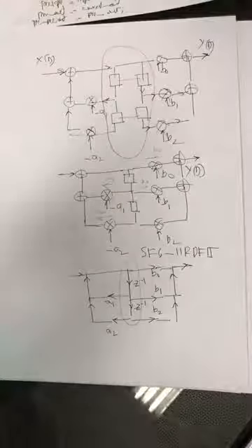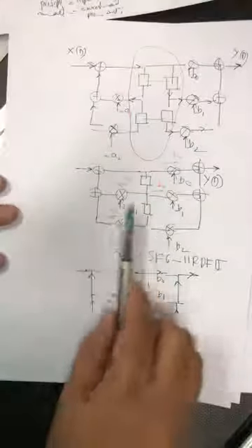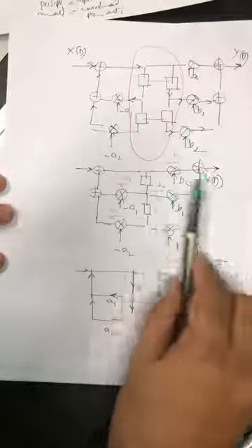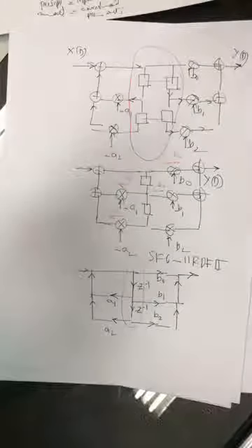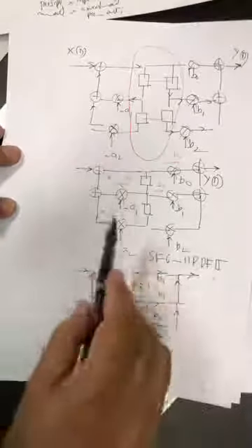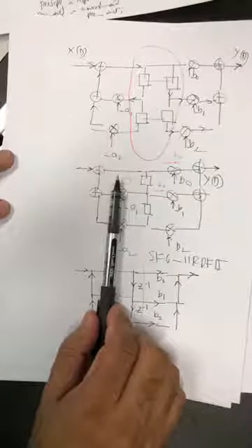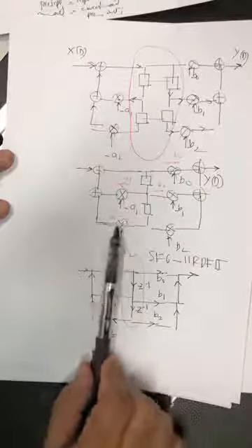Okay, but people did not like one thing in the direct form. What they did not like is that in direct form 1, they were doing the feed forward path first, and then they were doing the feedback path. Here they are doing the feedback path first, and then the feed forward path. So people wanted to perform the feed forward path first. Why? Because once you are doing a feedback path, your number of bits increases and it is more sensitive to these coefficients.